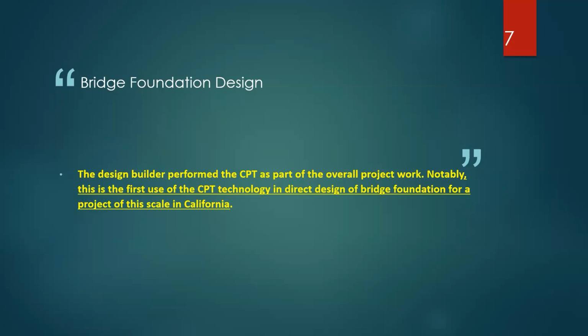Here I'm going to talk quickly about, and I'll talk later during the slides, bridge foundation design. As you know, the foundations for conventional bridges here in Southern California are typically designed using exploratory borings as part of the site investigation and site characterization. This project was the first use of CPT technology in the direct design of bridge foundations. By that I mean you take the CPT data and you design your foundations. You didn't have to worry about correlations or converting CPT data to SPTs and then designing your foundation. So this was the first use of CPT technology in direct design of bridge foundations for a project of this scale in California.